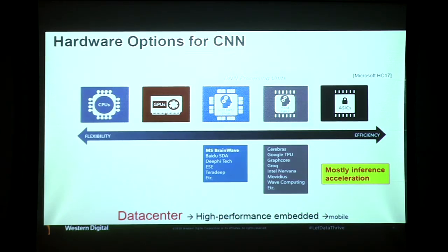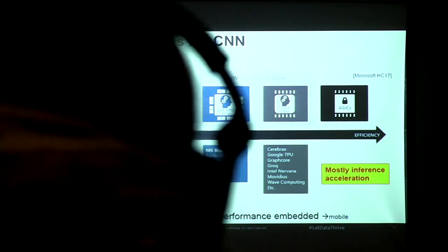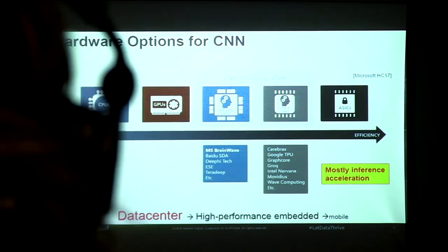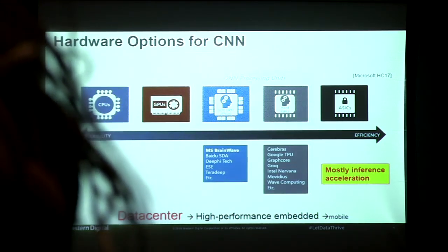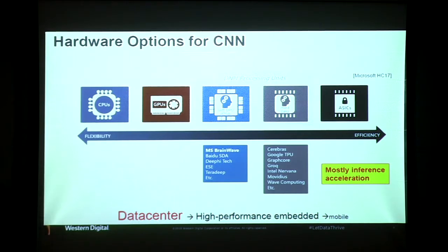At the far end of the spectrum, you can start thinking of building dedicated ASICs that will not focus on the normal arithmetic that you need for general purpose compute, but will implement all the primitives that you actually need in specific neural network acceleration problems. You'll focus on doing 8-bit and 16-bit arithmetic. If you are focused only on inference, you will perhaps add special DSP engines that you're familiar with, but again for different arithmetic, or maybe for convolution, matrix multiplication, etc. And then you'll have some fairly optimized hardware, and that's great, and people build that all the time.